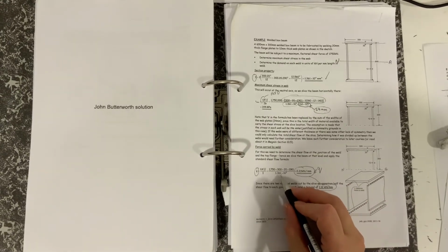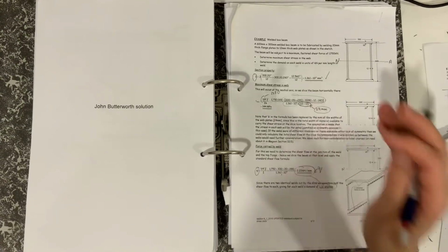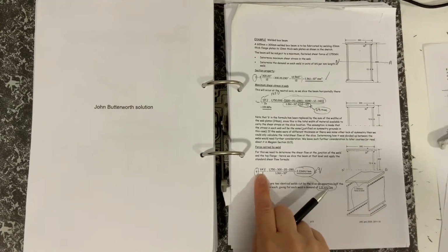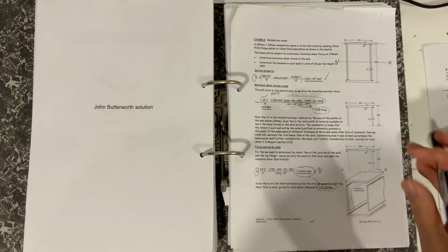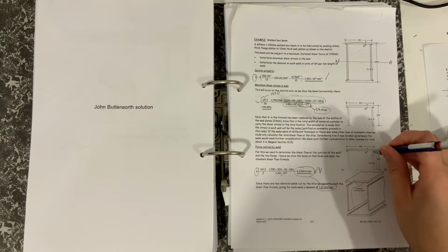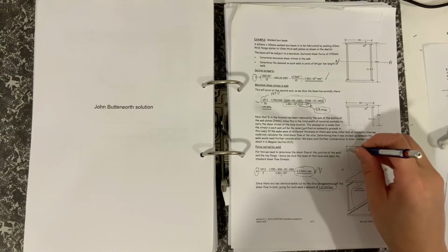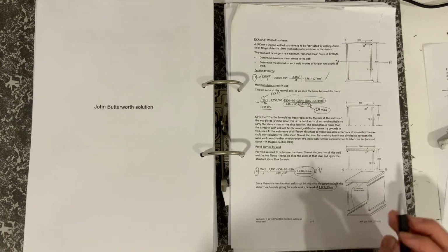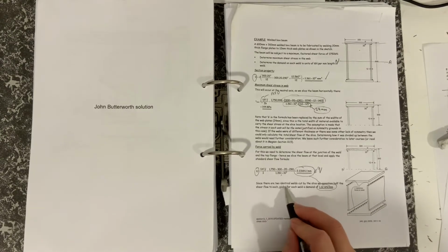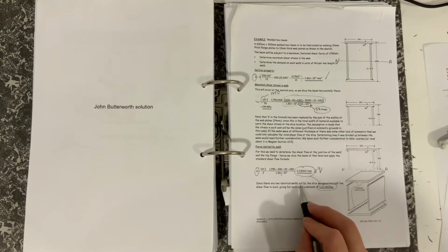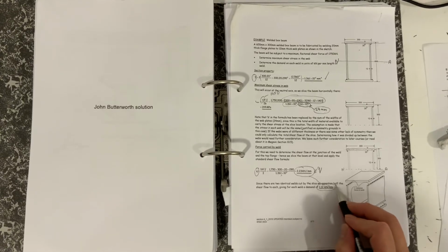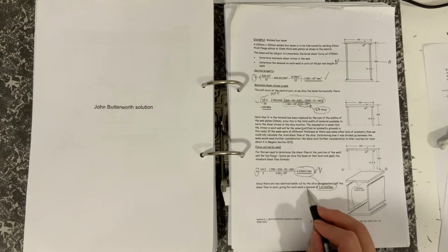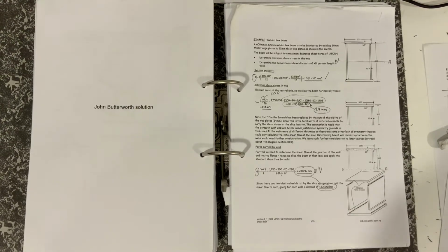And then I is of course the I of the whole section. So that's the expression for Q, which is the shear flow, or the shear that flows into the top section there. And we would say, since there are two identical welds, 1 and 2, cut by the slice, we apportion half the shear flow to each, giving for each weld a demand of 1.12 kilonewton per millimeter.